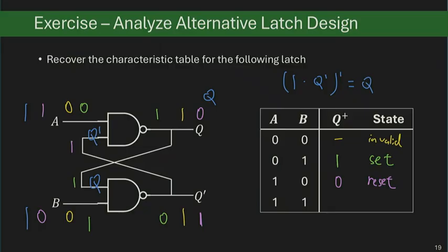If you don't like it, you can, of course, replace Q with 0, replace Q with a 1, and try both cases. At the bottom, 1 and Q, complemented, gives you Q prime, which is essentially the same as before. And with that, we know that Q stays Q, Q prime remains Q prime. And therefore, Q plus is Q, and that is my hold condition.